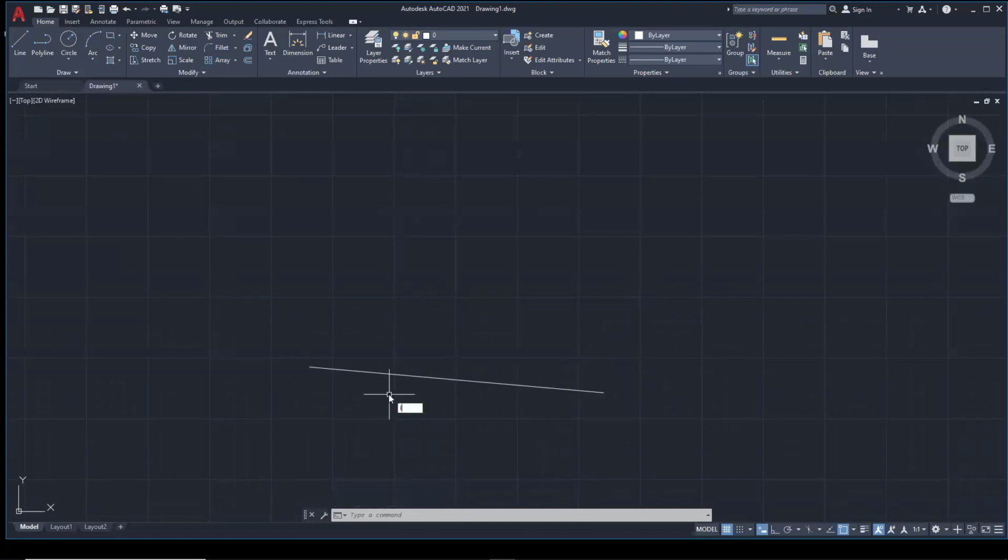If I want to create a line that has some inches in it, well, first of all, I could create that 1 foot line, or let's create a line that's 1 foot 1 inch long. I'll type 1 foot and then 1. I don't have to type the inch mark in AutoCAD. AutoCAD assumes that I'm typing in inches unless I use that foot mark, and that'll say, oh, okay, she wants to use feet.